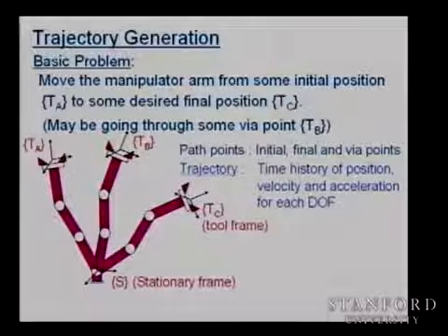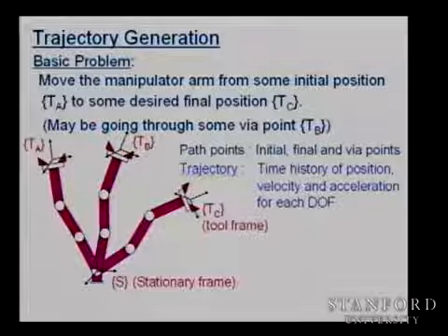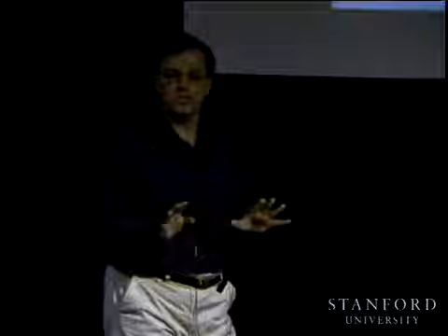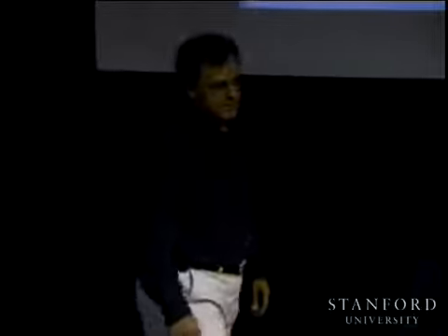For the purposes of this lecture and basically this class, we'll be planning each of the degrees of freedom independently and then assume that the motion is realizable as a whole, okay? Because once you put them all together, it starts getting very complicated. So for each of the degrees of freedom, we'll be planning the trajectory.